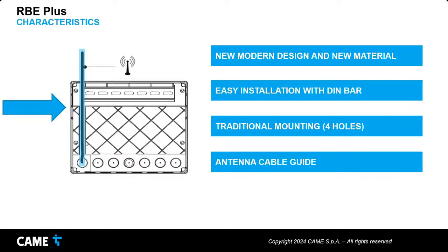That's why we may use the antenna going into the back side of the plastic box and reaching the upper side of it, in order to be placed in a better way to capture a good signal strength. Of course, right now we are talking about the actual GSM module, which is a 2G version.